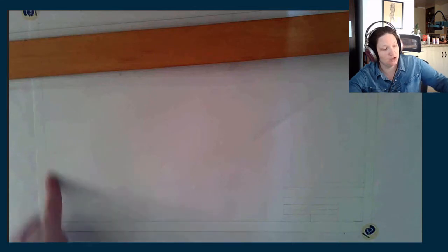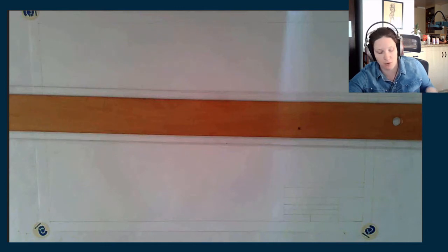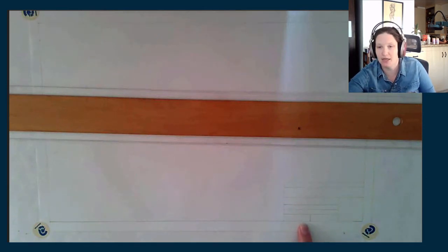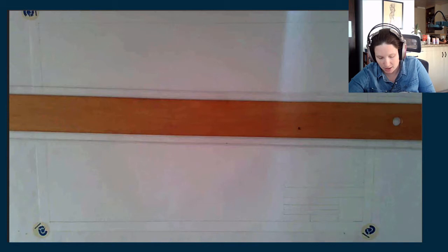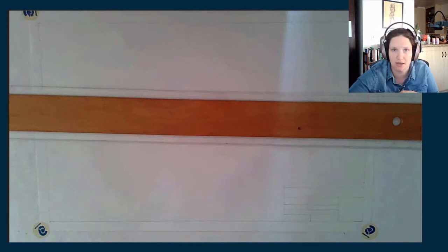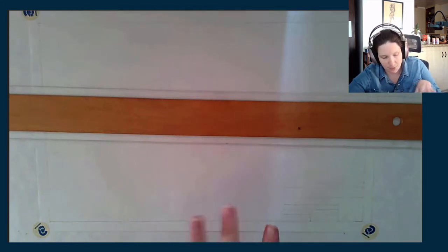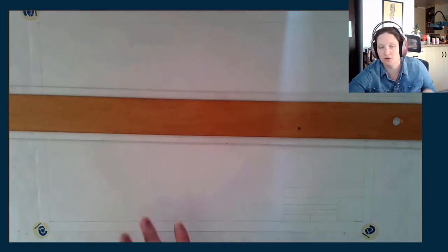Great. So that's your drawing preparation, right? Do your sheet border, your 1/2 inch sheet border, all the way around your plate, just like we did before, and then put in the layout of the title block. Don't fill in that lettering until you're done with everything because that is the most apt to smudge because it's just that real soft HB lead. But layout of the sheet, great.